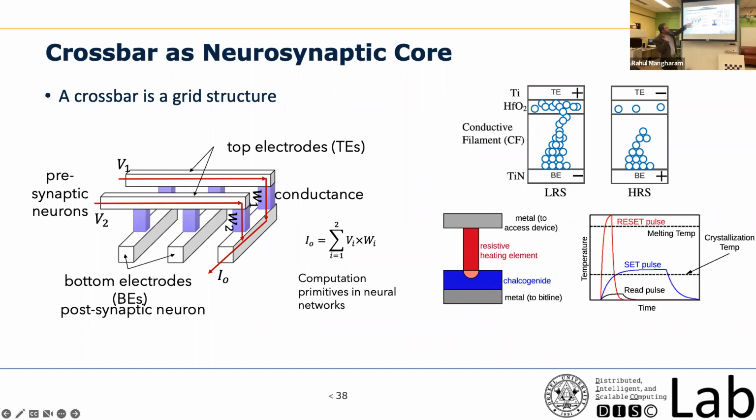Anyway, moving forward, one of the interesting things you can do is implement a crossbar kind of hardware, where you have these horizontal bars, as I was mentioning, which propagate voltage. We use a little bit of circuit theory: voltage, and the weights are programmed as conductance. Voltage multiplied by conductance is current. So you get a current, and in parallel every current is accumulating, Kirchhoff's current law. The architecture becomes completely parallel.